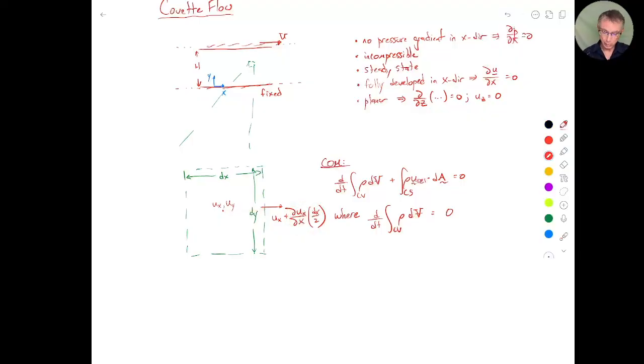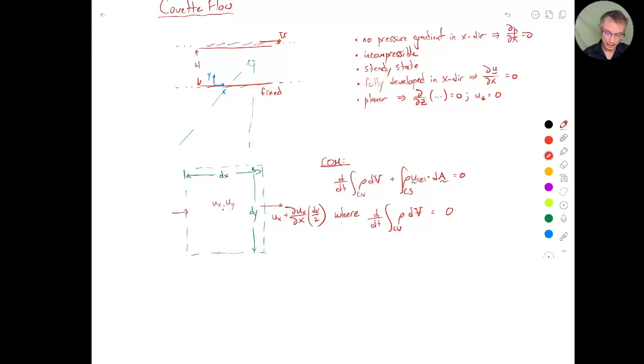We can do the same thing over on the left-hand side. So to find the velocity there, I'll say it's ux is what I start with at the center. I've started at the center and now I'm moving in the x direction that way. So I'm going to add in how my x velocity changes in the x direction and then multiply it by how far I've moved to go from the center to the left-hand side. So that distance is minus dx over 2. And then let me do the y velocity as well while we're at it.